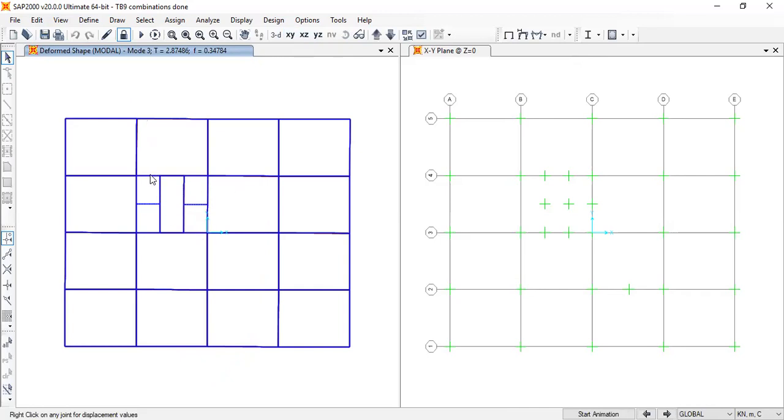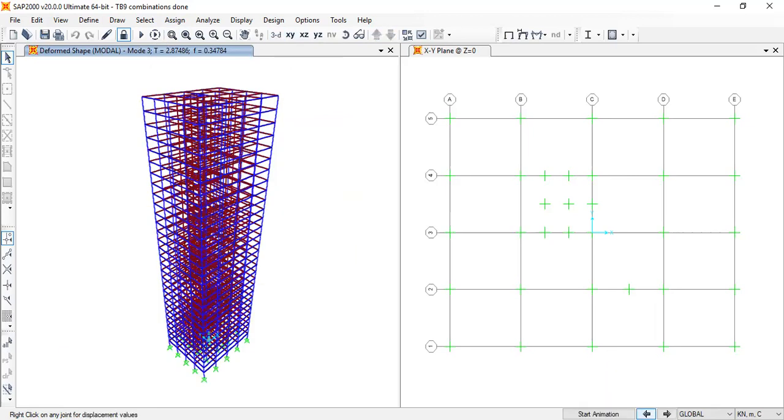We arranged the shear walls to bring the shear center of this building to the center, so we can do a calculation for this shear wall arrangement using I values. We will do it later in the structural forms. So I took the shear center to the center of the building, so the mode is now non-twisting.